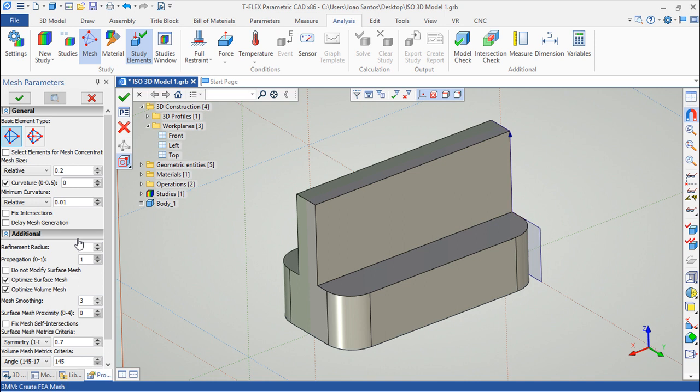There are a couple of interesting points. It's also important to have some experience with different modules, with different examples. It helps. But there are a couple of parameters among all of these that are important, and we need to look at them. The first important notion is that we can have several types of meshes, and we can go through them through this option. So tetrahedrons or curvilinear tetrahedrons.